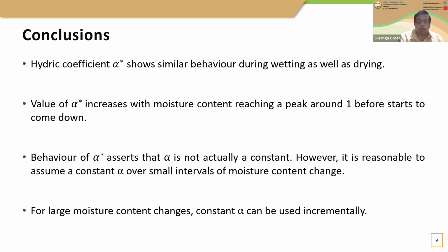Now, many people have used alpha, the hydric constant, in desiccation cracking analysis. People use hydric constant alpha as actually a constant, but the behavior of alpha star asserts that alpha is not actually a constant. It has a variable nature.